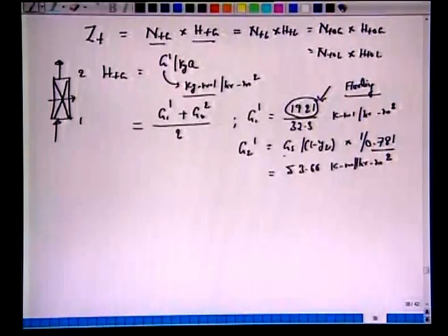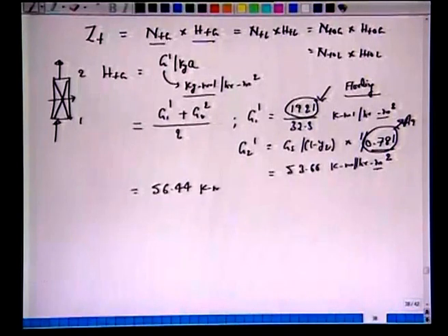This was kilomole per hour, divided by the cross sectional area, to give us kilomole per hour per meter square at 1 and 2. From this, a simple calculation will give us 56.44 as the average mass flow rate based on the empty, superficial or cross sectional area of this column.